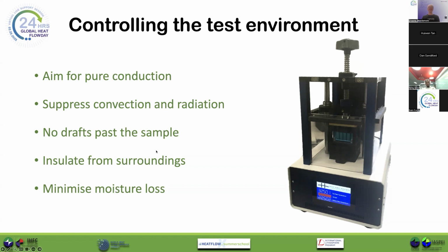Thermally insulate the sample. So here's a divided bar instrument, and within the divider bar here, you can see foam insulation, which is actually wrapped around a sample in here. So that insulation is to thermally isolate the sample during a measurement. And it also has the effect, if that sample has been water saturated, to minimize the evaporative loss of water during a measurement as well. And on the outside of this divider bar, there are also secondary shields to stop air currents from blowing past. So we have a thermal shield and then also an air shield.